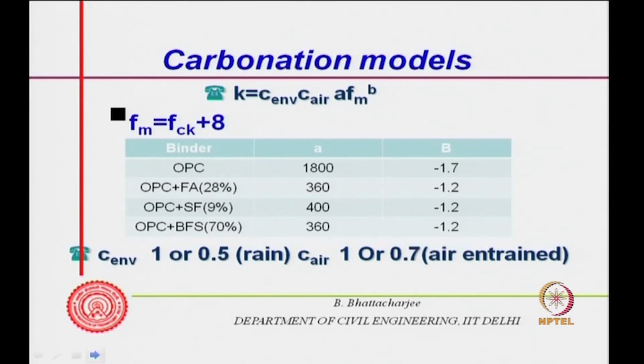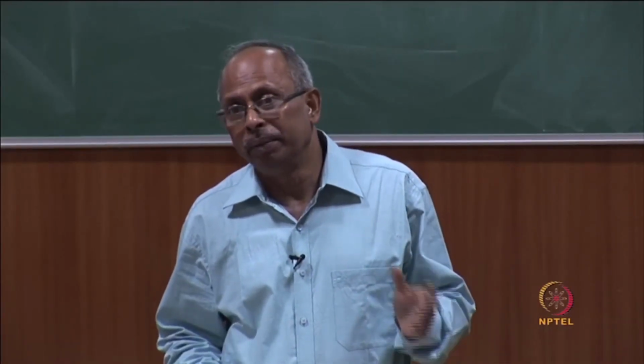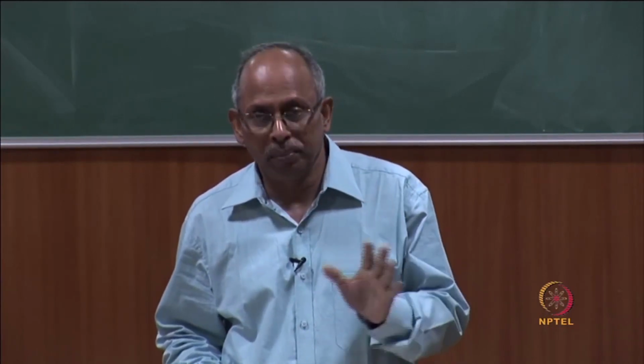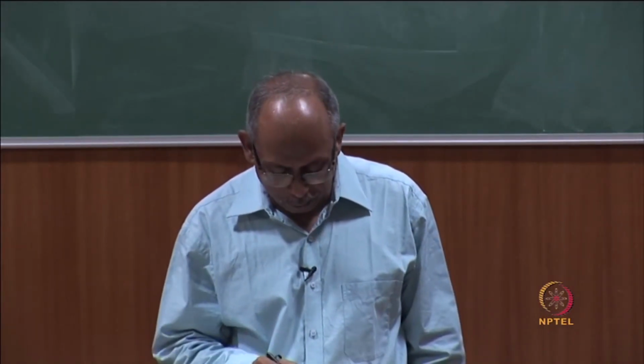Their resistivity is high for this kind of material. Whenever you add pozzolanic material, resistivity increases significantly, as we shall see later on, and therefore they do not create much of a problem when it comes to kinetics of corrosion. So, they have a tendency to depassivate, but when it comes to kinetics they might even prove better.